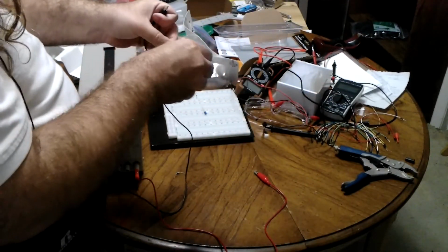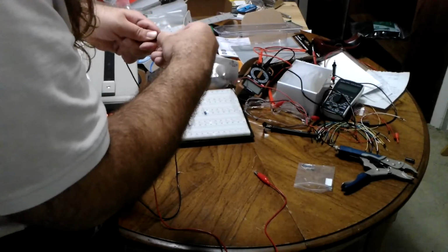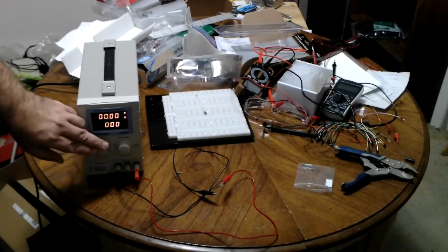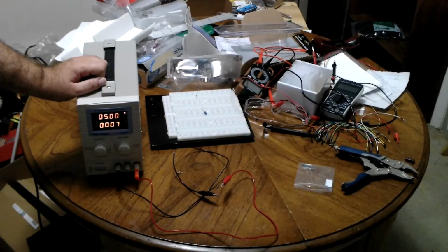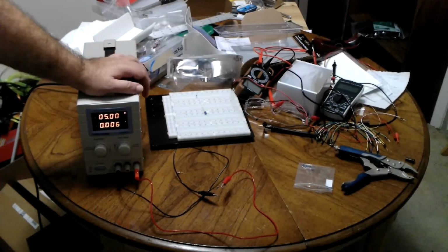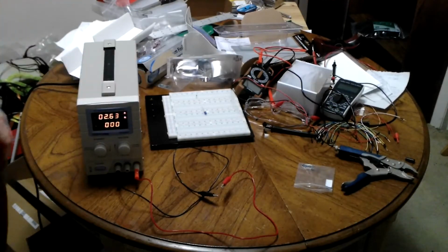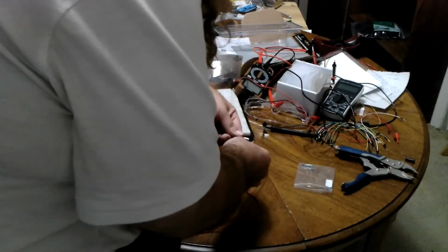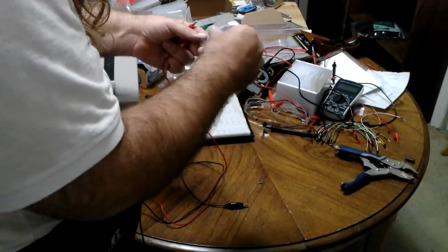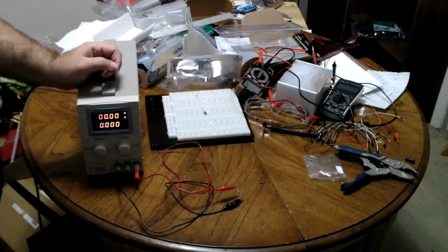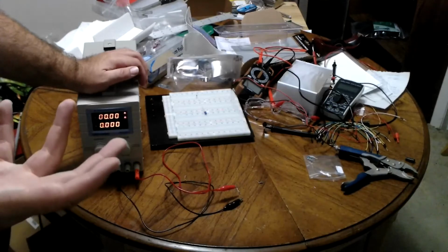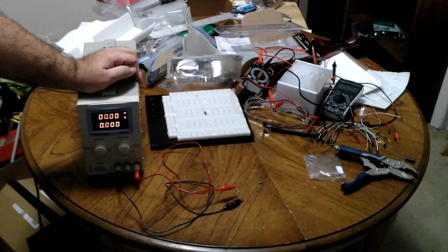Let's try something else. And by something else, I mean another 1 ohm resistor. Let's see if we have better luck this time. Let's see what happens. About the same thing. And this one is down to 6 milliamps. So let's try one more time, a little more slowly. Perhaps it is the speed with which I am increasing the amperage that is causing the rapid failure. And if you're worried about me wasting money, because you buy them in a pack, each of these resistors costs less than 1 cent.